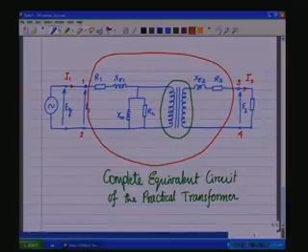Now I1 flows through the primary leads into the transformer, it gets split here as I0 and it goes through here as IP, ideal, I primary ideal, and on the secondary side you have the current I2 which is flowing through, and here you have IM, the magnetizing component, IC, the core loss component of the current.